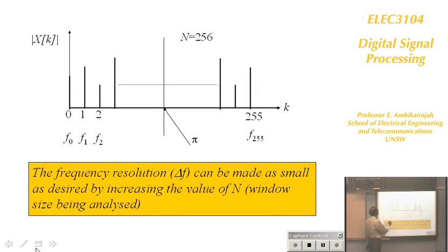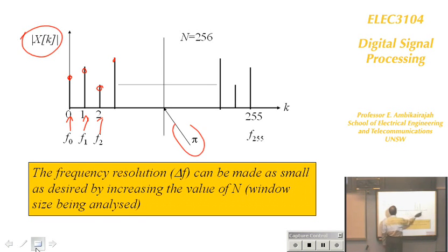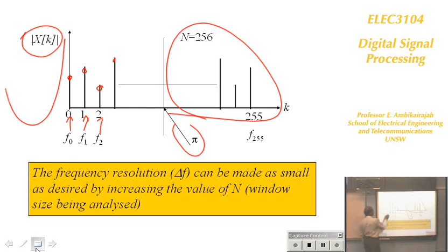So when you do the magnitude response, this is how you see it. You see your DC value here, then the first frequency, that's S0, then your second frequency, third frequency, and then you get to pi, and then these all will repeat, all symmetrical, because this belongs to this side. So normally you plot only 0 to pi.